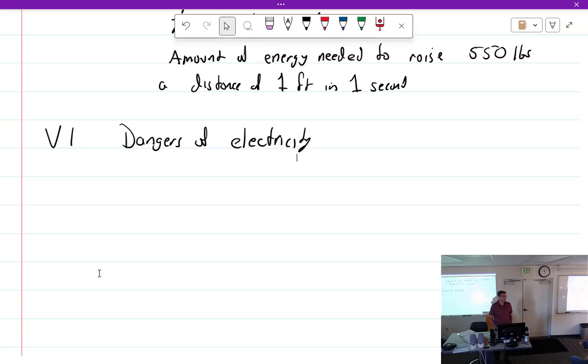I don't know, maybe you guys have seen it, maybe you haven't, but it's where we do non-destructive testing on steel parts. So if I put a steel part in there, such as a crankshaft, I'm going to put it between 2 copper braided lines, and I will energize it, and I will put 1,000 amps per 1 inch cross section. So a 2-inch crankshaft is going to get 2,000 amps running through it.